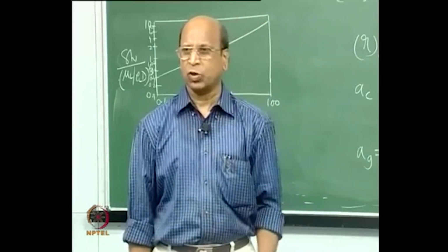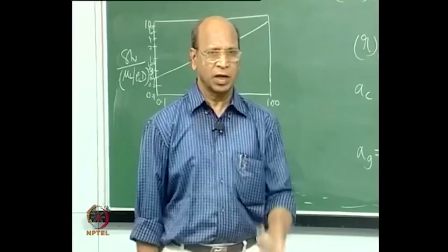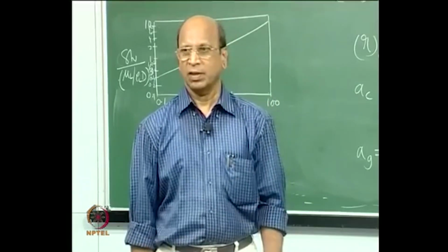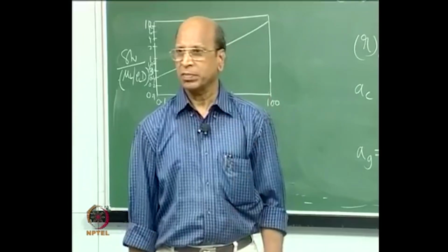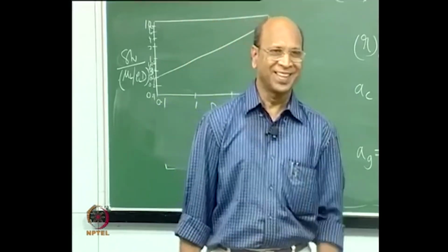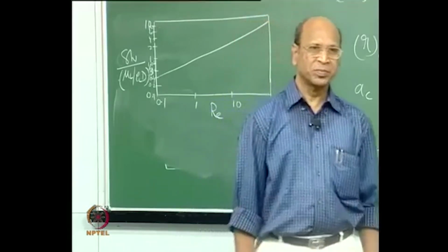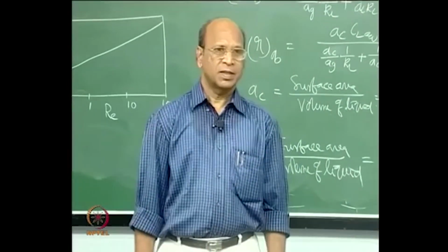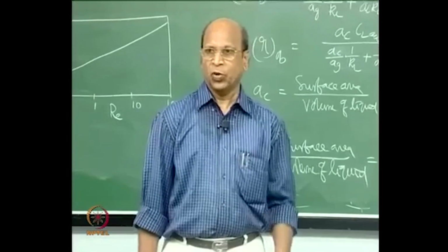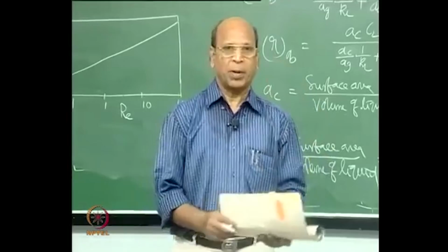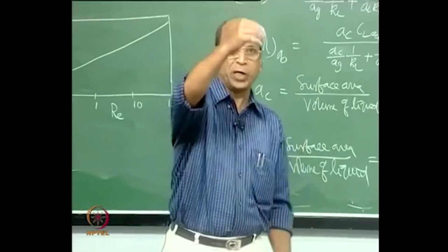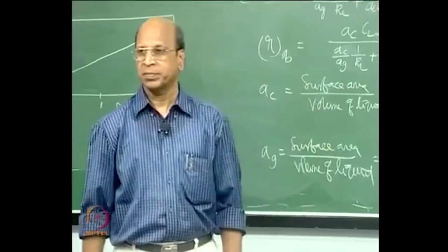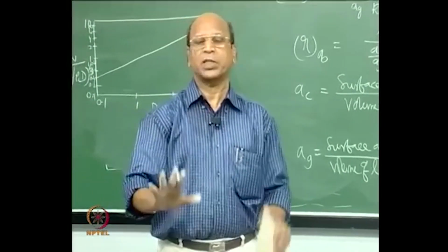What is the normal hold up we use in a rotary kiln? Luckily they are solids, they are not changing. So that is why you said that it must be less than 10%. Okay. So why can't you use 90%? Yes, Kavya, why can't you use 90%? They will be contacting. Mixing won't happen. Yes, mixing will not happen, and the way you expect the particle to be lifted to the top and then fall, again lifted to the top, again fall, that kind of beautiful motion is not there. So that is why 10% or less than 10% is fantastic.